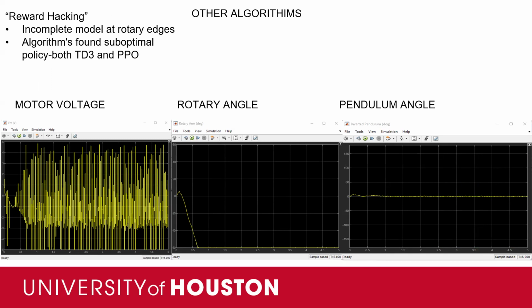Now you can see from this, the pendulum angle 0 is full inverted. This algorithm is balancing this inverted pendulum on this nonlinear model. However, looking at the middle scope, it's doing that by going outside, or to the border of, the envelope. We don't want it to break. Something that can be noted: you can adjust that window and adjust the stop training criteria to help disincentivize it from going into this area. That wasn't done for this training session, so there's future work to try and limit this behavior.